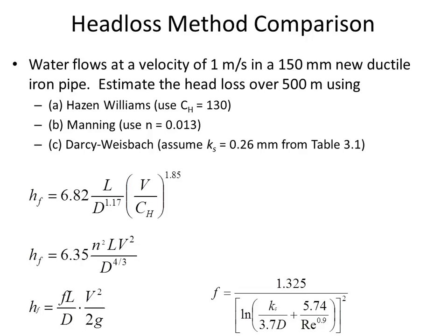The fact that the wetted perimeter is higher than most of the situations where Manning's equation is used, coupled with the lower velocity, where Manning's equation was really calibrated and these n values were determined for typical flow conditions. So it's really all in the n value.